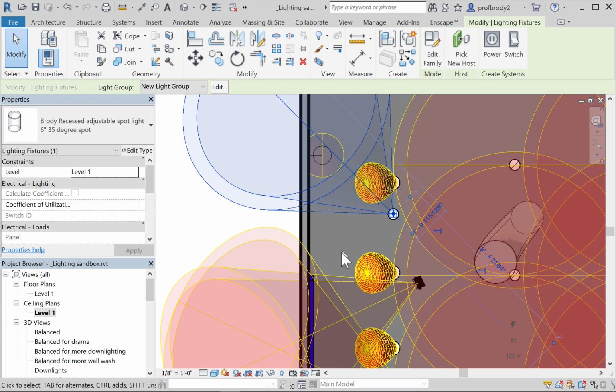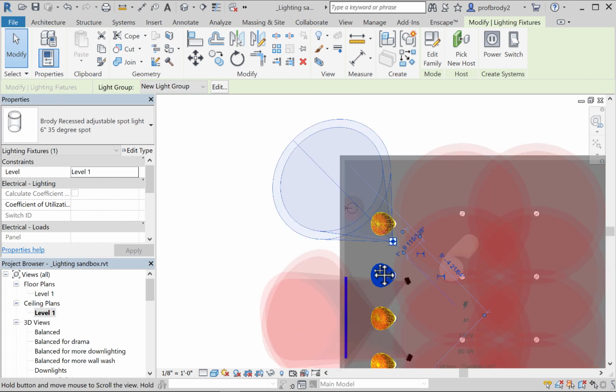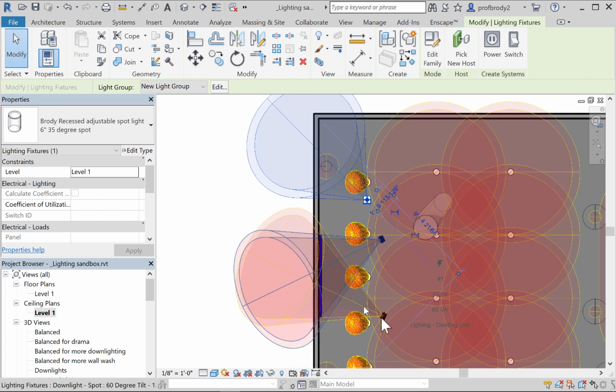This one here is a recessed one. So if you're going with all recessed circles in your ceiling, this one will match that. Again, you're going to want to just rotate it in reflected ceiling plan. And if the light is spilling too much or not narrow enough, you can modify the properties to change the angles.